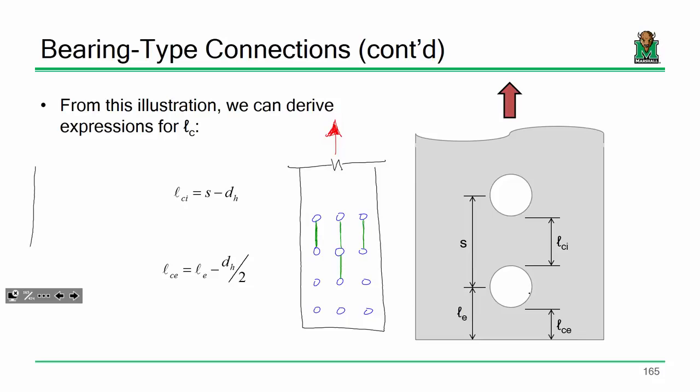So, for instance, if I've got this, and I've got, let's say, 1, 2, 3, 4, 5, right? So for these 2 on the bottom, my LC would sort of be that distance right there, and the same one for this one, so I'd maybe treat those 2 bolts as the same. And then the center one, my LC is going to be whatever that distance is right there, and then these 2 up here, I'm going to have another one, and something like that. It doesn't become technically more challenging. It just becomes a bookkeeping issue.